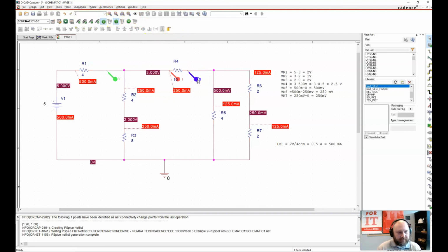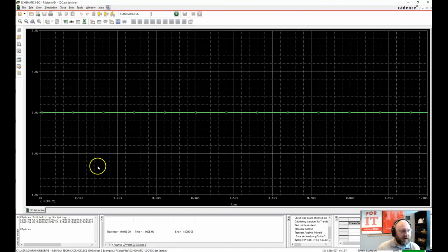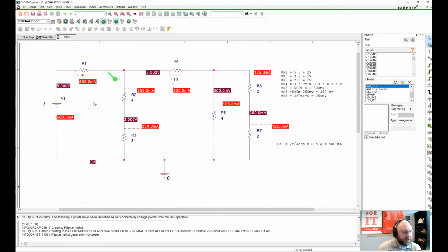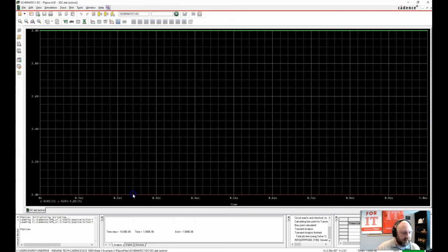All right, so let me take a couple of these off here. And if you delete these probes by just selecting and deleting them, they disappear from the graph. One more I want to show you here. The last one I want to show you is this differential probe. It's the second one in here, voltage differential markers. These you have to put at 2 points. Now if I do this and I put 1, notice it has V plus here, and then a V minus on the other side, and it's red, so I'm going to go back and look at the red curve here now.